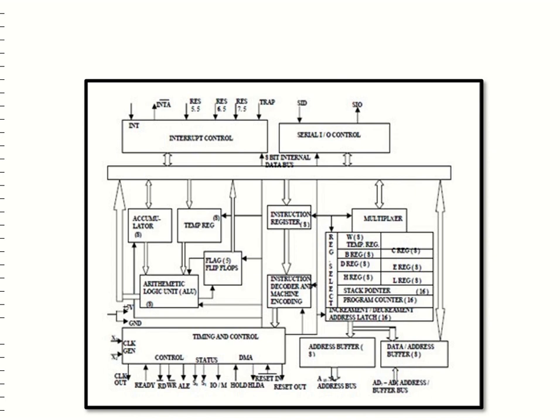Program counter. It is a 16-bit register used to store the memory address location of the next instruction to be executed. The microprocessor increments the program counter whenever an instruction is being executed, so that the program counter points to the memory address of the next instruction that is going to be executed. Stack pointer. It is also a 16-bit register, works like a stack, which is always incremented or decremented by 2 during a push and pop operation.